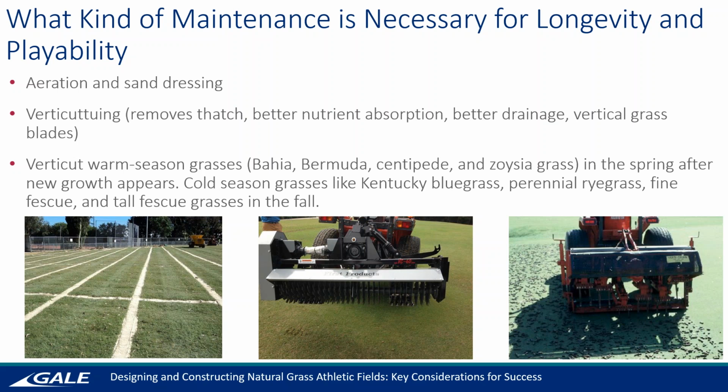Your natural grass fields will get compacted over time, especially if they're native soils, and that will not only increase the compaction, it will increase the hardness and cause a potential safety concern for athletes with impact attenuation, but also slow down drainage vertically, and not being able to get drainage into the subsoil, into the root zones for that matter, and not being able to have air voids so the roots can be ventilated as well for proper growth.